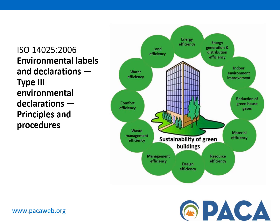Type 3 environmental declarations are described in ISO 14025-2006 and are primarily intended for use in business-to-business communication, but their use in business-to-consumer communication under certain conditions is not precluded. ISO 21930-2017 covers sustainability in buildings and civil engineering works. It provides core rules for environmental product declarations of construction products and services. It complements ISO 14025 by providing specific requirements for the EPD of construction products and services.